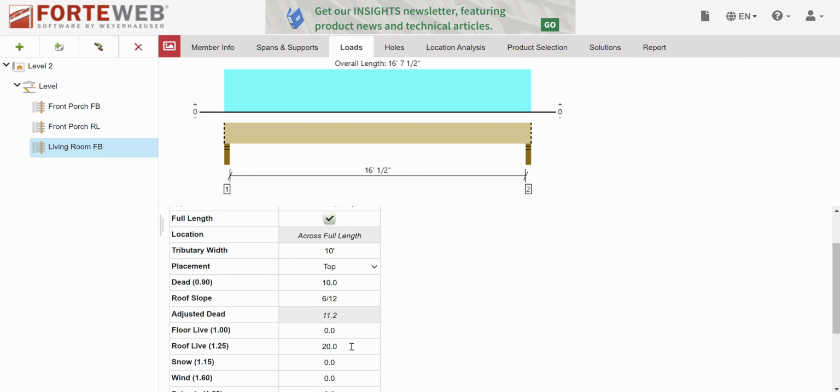the roof assembly is like the shingles, because these numbers can deviate depending on what materials you're using if you're looking at a special chart. But you've got shingles, usually 2x6 rafters, and the OSB or plywood, whatever's on the roof sheathing. And then that's it, because you have an attic and you're not covering that up. But we're adding sheetrock to that because this is a vaulted ceiling.